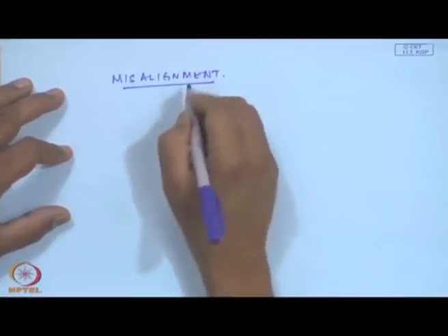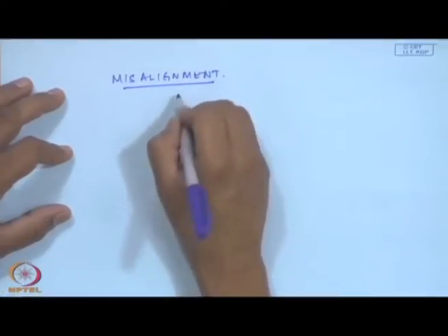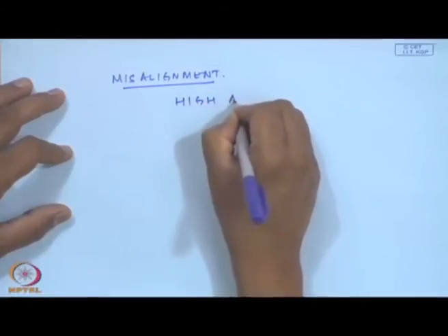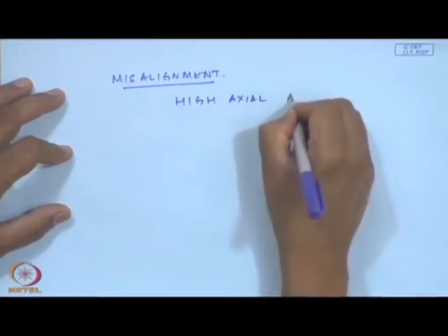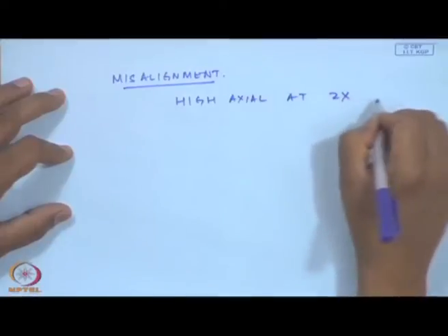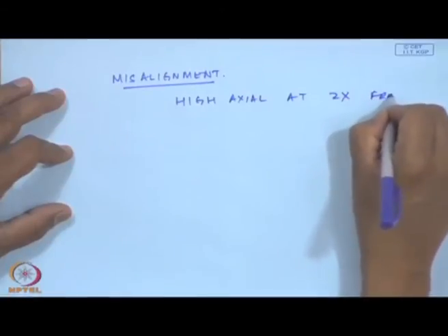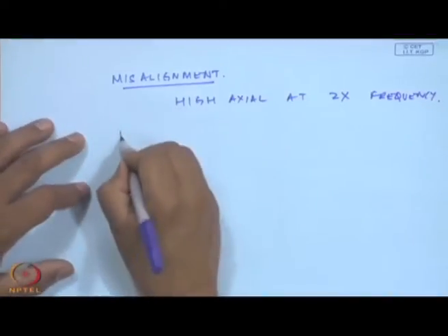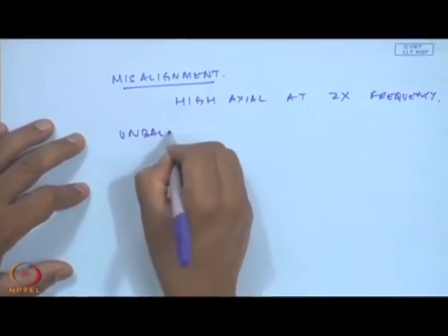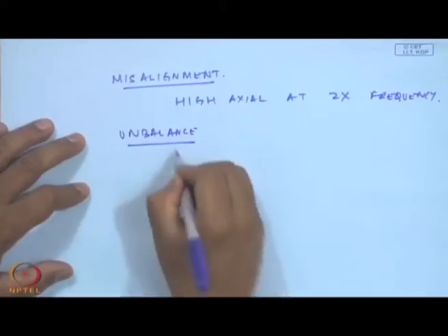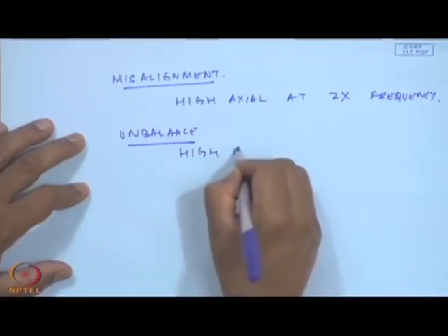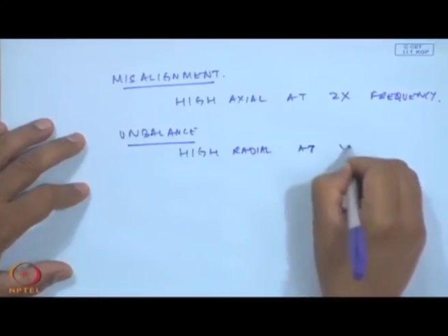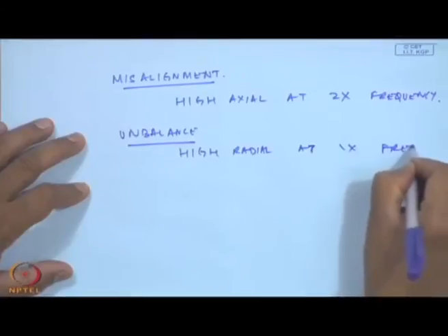as opposed to the unbalance, where it was strongly radial, here it is high axial at 2x frequency. If you recall, unbalance was high radial at 1x frequency.